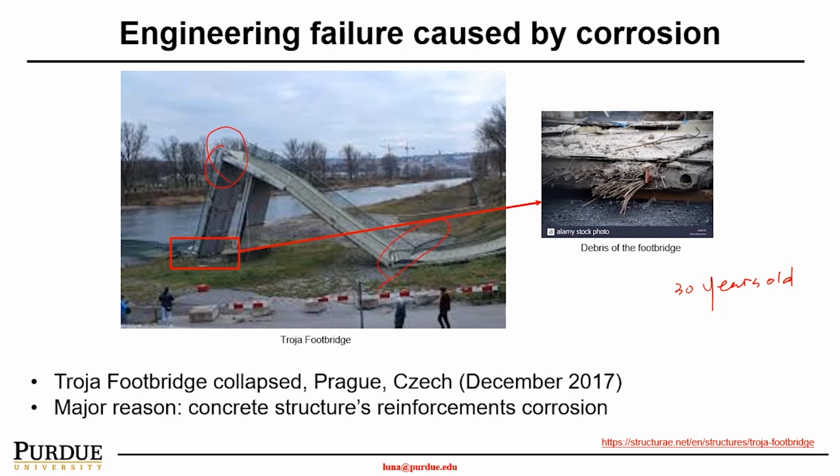So the rebar has been completely exposed after the fracture surface. As you can see, corrosion clearly led to the compression strength being reduced, so it cannot take the load. What is really interesting here, I would like to point out, just an anecdote: this bridge had been instrumented with sensors to measure the deflection 3 weeks before the collapse.